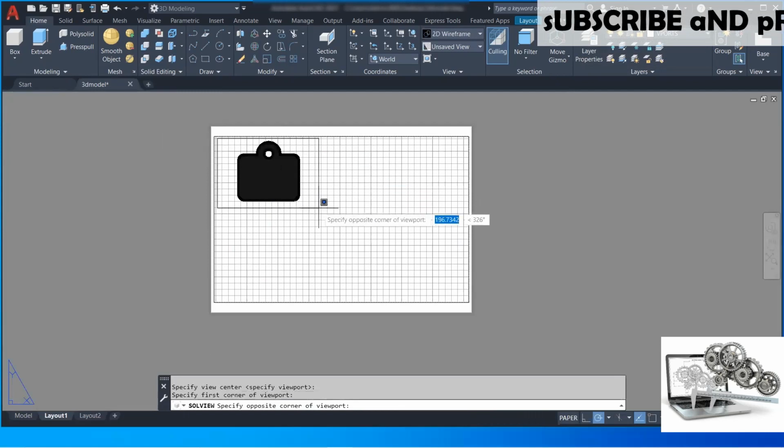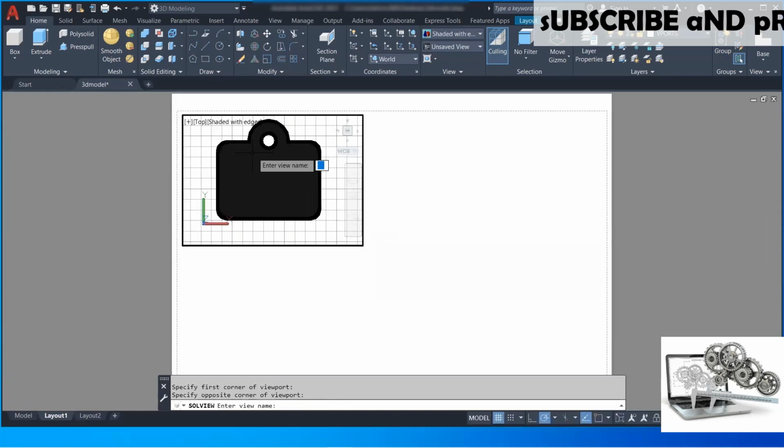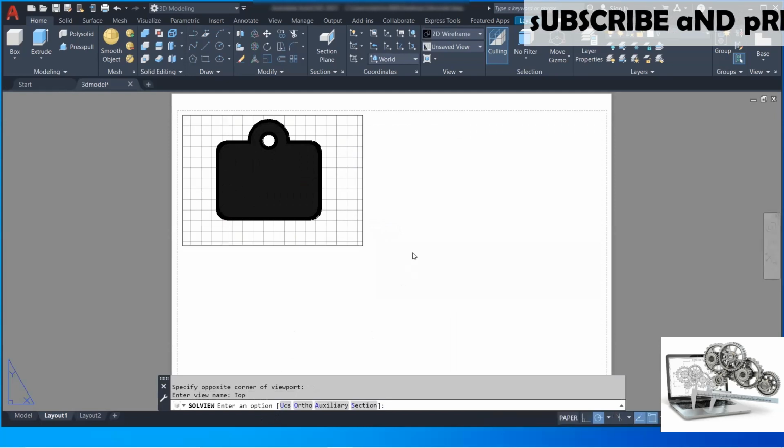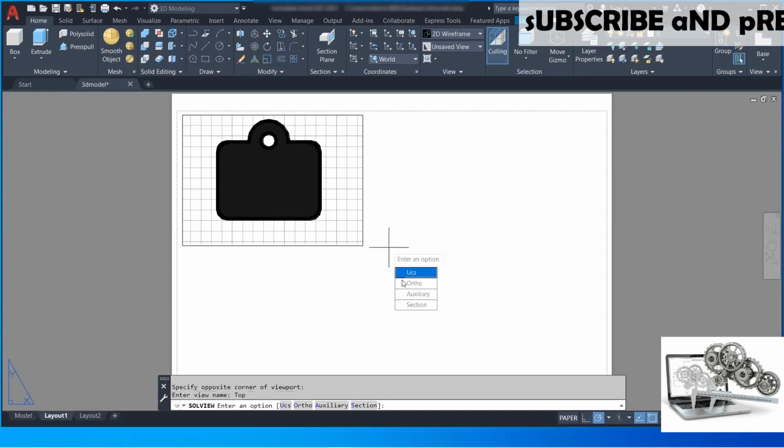Then it is asking you for the first corner. So click on the upper left corner. Yes, just like this you can create a viewport. Give the name. Here we are using the third angle method, so give the name as top view. Press enter.